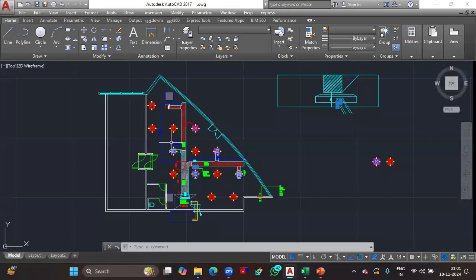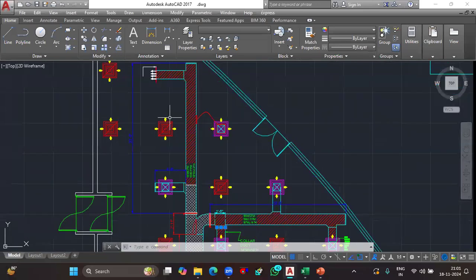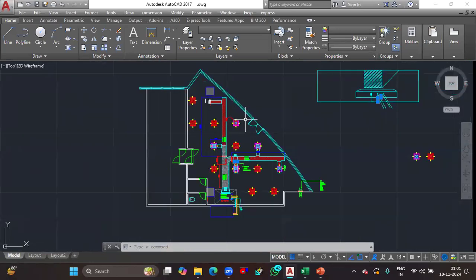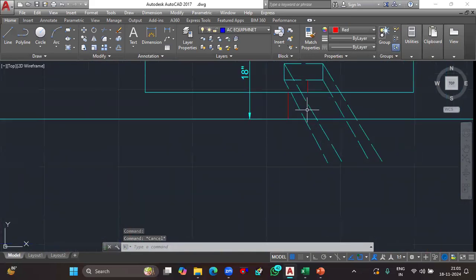Guys, actually, we have 6 number of diffusers, isn't it? So here I've shown grills and FAB. No need to concern. It has to be considered an entirety of diffusers with full dropper connection. So probably 6 number of droppers will be there, isn't it? So in those droppers, we need to find out the length. Here, dropper means a vertical duct that goes downwards, isn't it?